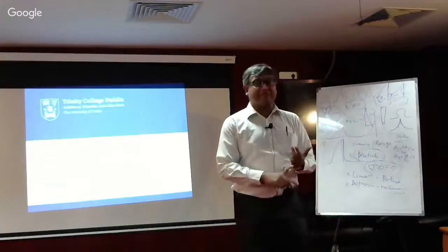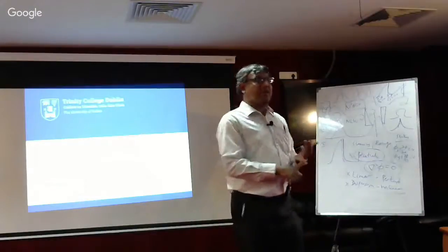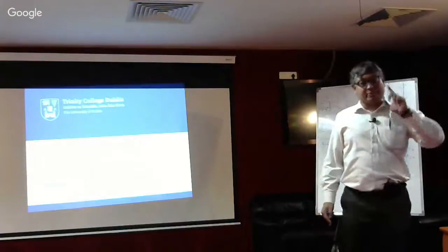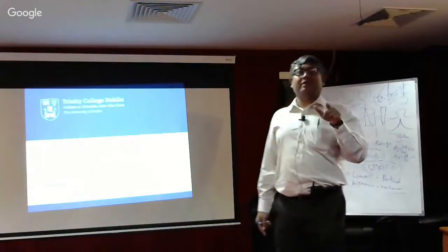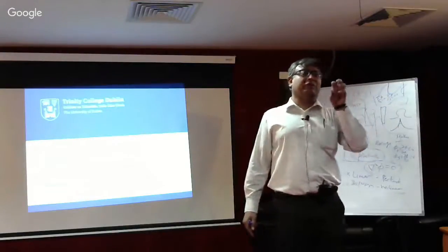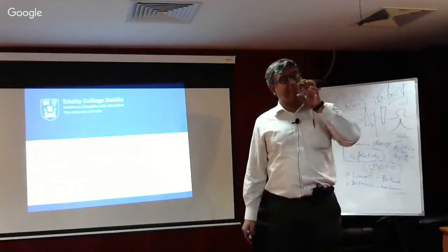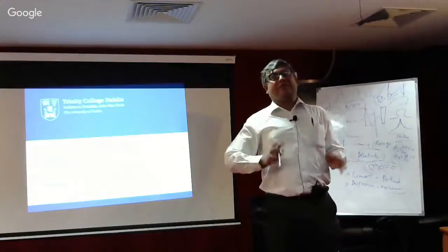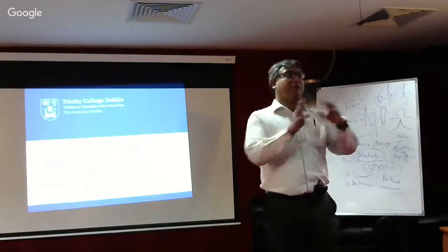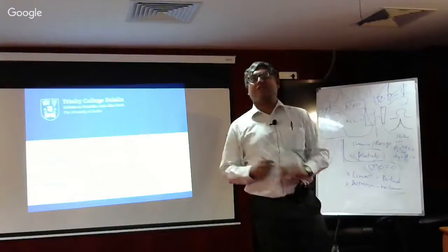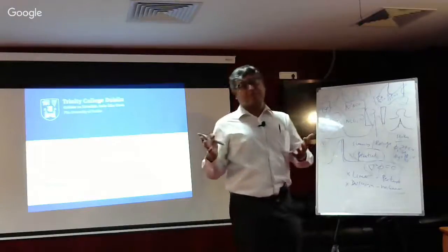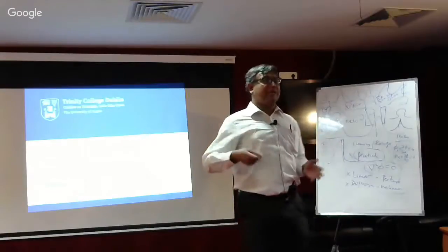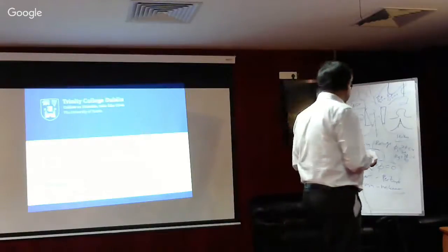So you have dissipative systems and dispersive systems. And if you see the Navier-Stokes equation, you had a term U ∂U/∂x, which is the dispersion term. You had the term ∂²U/∂x² associated with your viscosity. That is the dissipating term. So in general, in various physical phenomena, somewhere you find the dispersion dominates, somewhere you find the dissipation dominates. And even in a single problem, there are regions where one dominates the other. So the interaction between these two also is quite common.